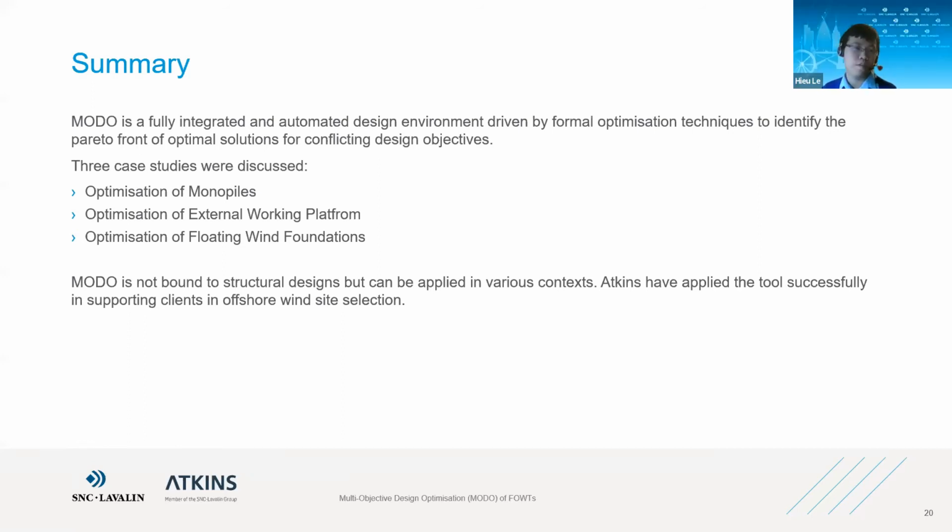Yeah, in terms of prevalent designs, you've possibly heard that there are only two types of floating wind that currently have, not a demonstration, but pre-commercial projects. One is the Hywind spar concept, and the other is the WindFloat concept from Principle Power, which is quite well represented in different projects nowadays. And there are quite a few of them as demonstration projects at the moment.